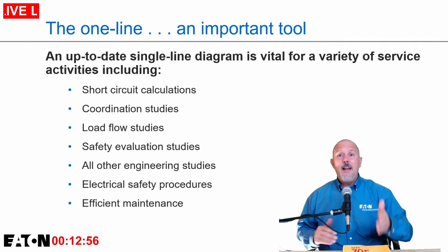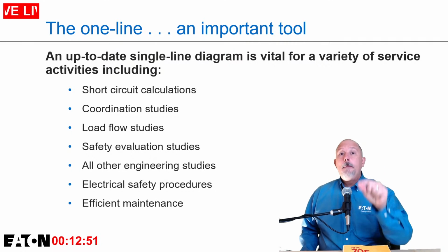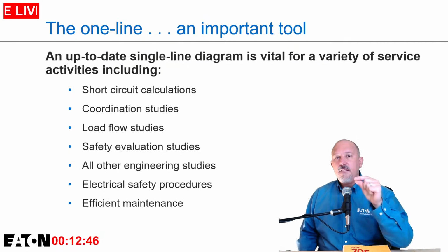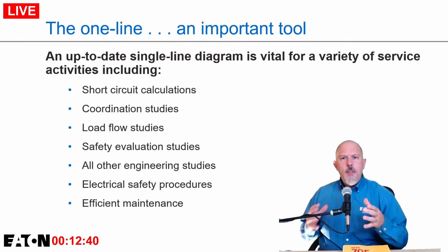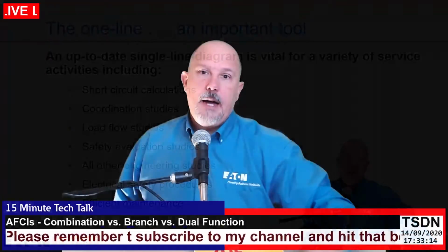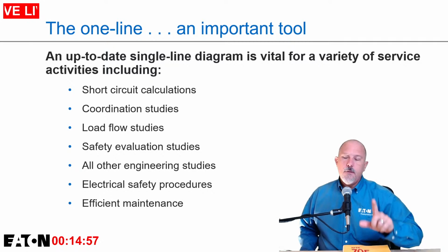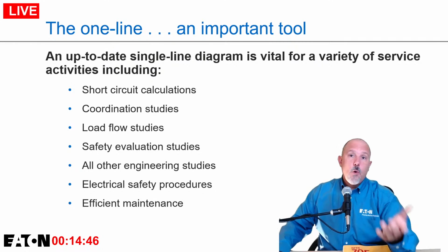In fact, I would argue that you should have somebody in your facility responsible for maintaining that one line diagram and intimately involved with the maintenance of that diagram, because that individual is going to know the power distribution system in your facility like the back of their hand. They're going to be the go-to person should you have to do some maintenance or any work in the facility.